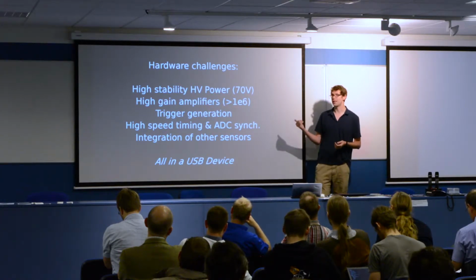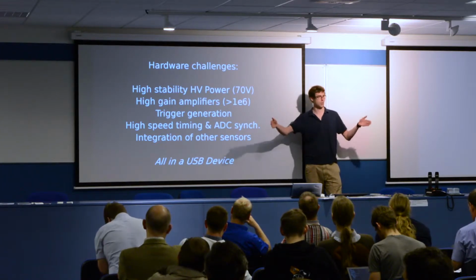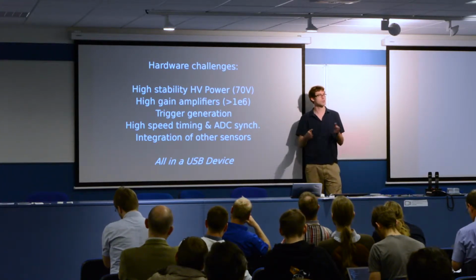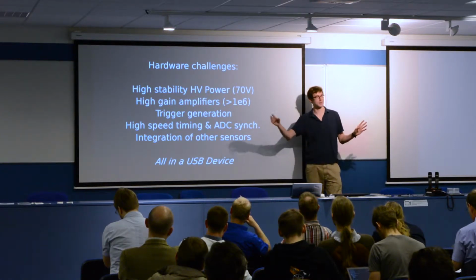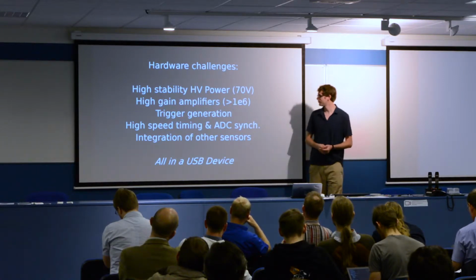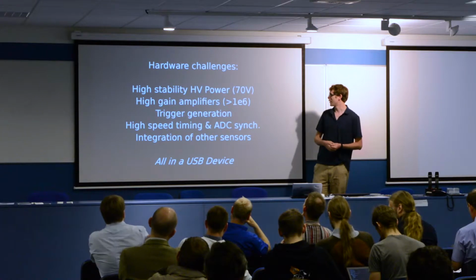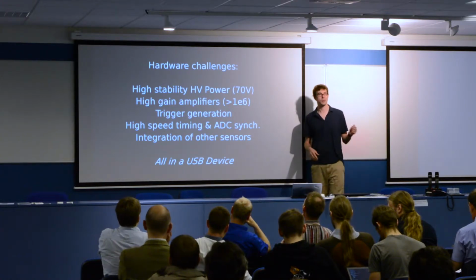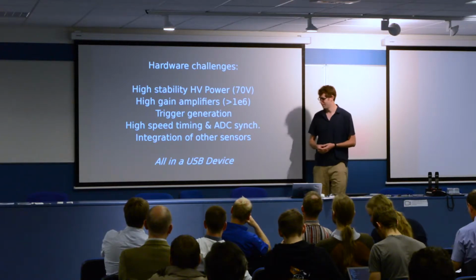And we need to synchronize the ADC effectively to break up our time span of, say, 1 second into a number of buckets, so we can say that we have an event in this space at this time and in another space at another time, so that we can correlate the two to say that they're actually linked. And we have a lot of sensors to integrate as part of the overall science package. And all of this is going to have a USB plug on the end of it to plug into a Raspberry Pi.